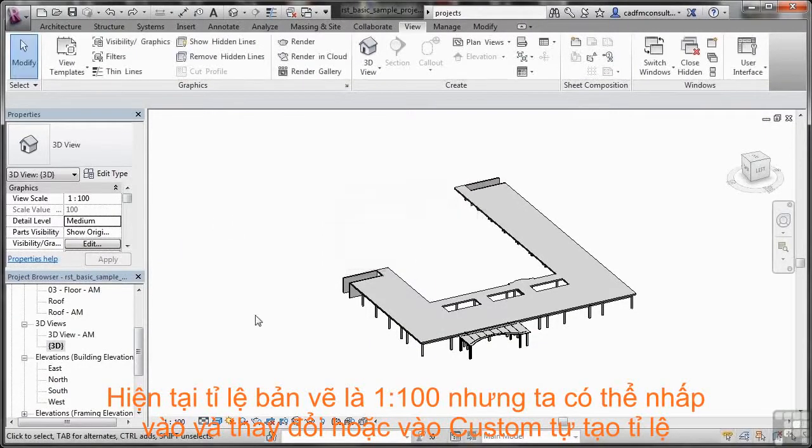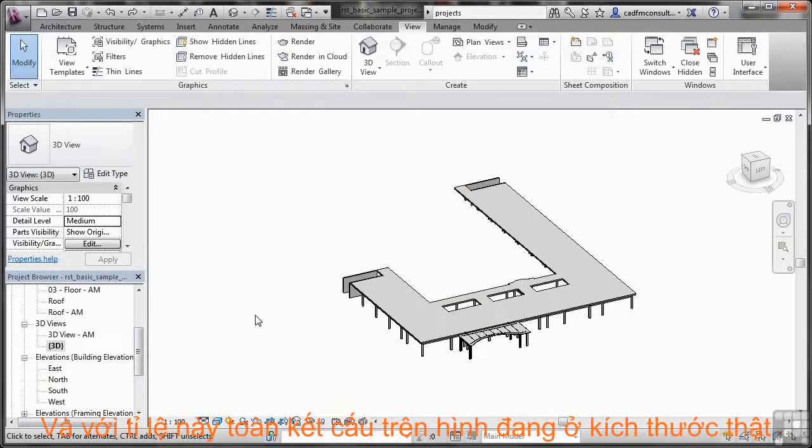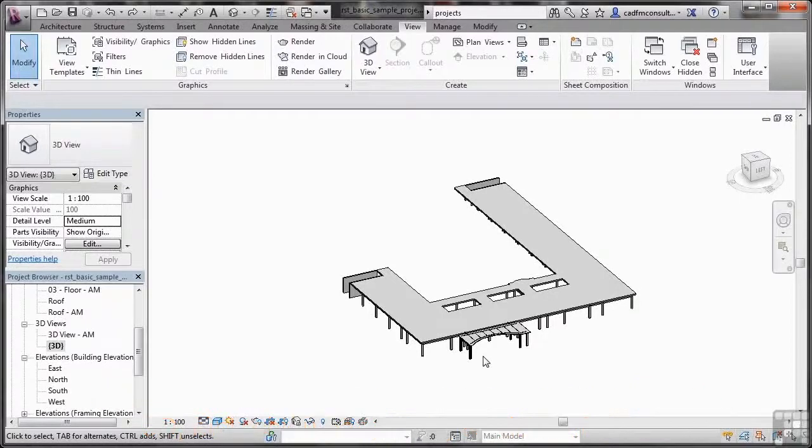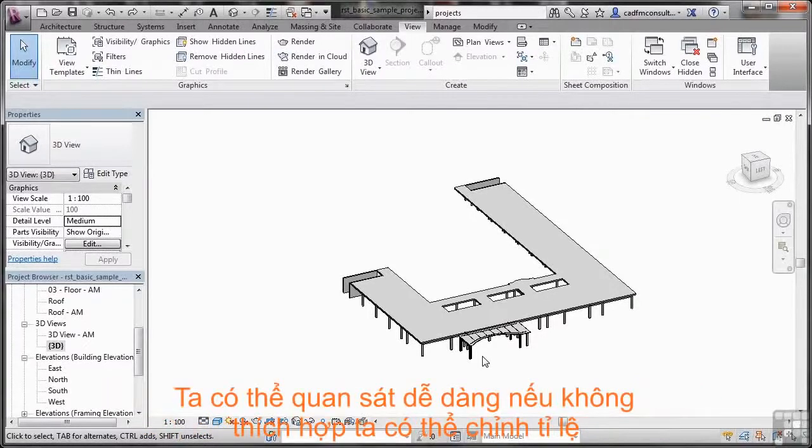So that's your scale. Now, when you're setting that scale, everything you draw here is still full size. What that scale does is it allows you to take that view, whether it be a 3D view, an elevation, a plan, and then put it onto the Revit drawing sheet later on in the project. We will cover that later, setting up sheets and scales and views and so on, and you'll see how simplistic it is when you're setting up those scales.